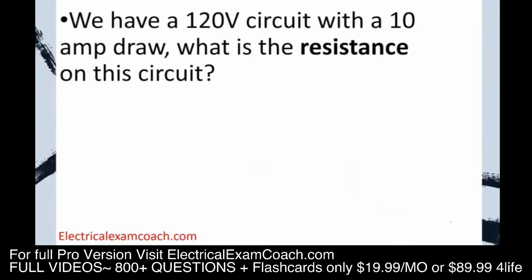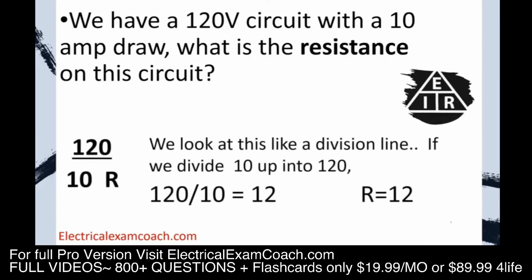Let's imagine that we have a 120 volt circuit with a 10 amp draw. What is the resistance on this circuit? Well, what I love about formulas is you just plug in what you know. Draw it exactly how it looks. I put my 120 on top. I know my current. I set it up in this manner. Then all I have to do is divide.